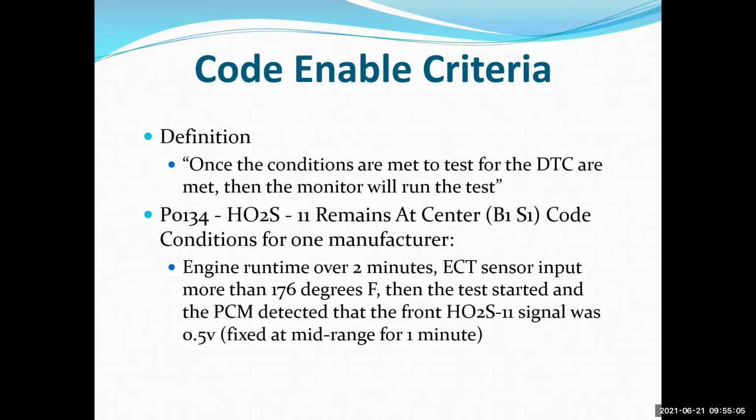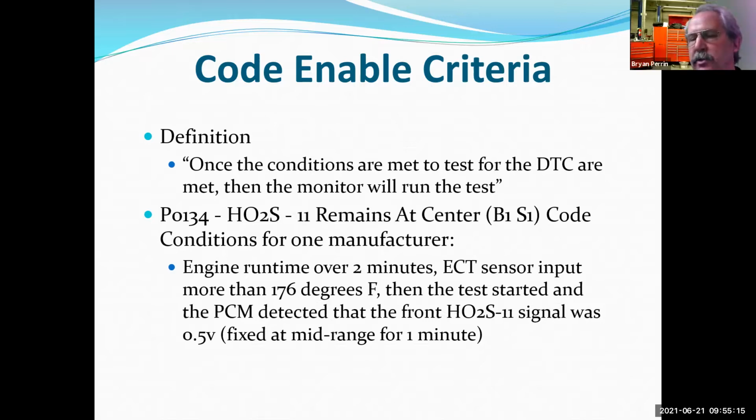And these thresholds, Sir Brian, these are set by the manufacturer and in the system already. So if these are not met, that's when this code alert will come out, right? Exactly. So this is completely set by each individual manufacturer for each code. So I could have the same code number and one manufacturer may set this after 2 minutes. Another one may set it after 15 seconds, right?